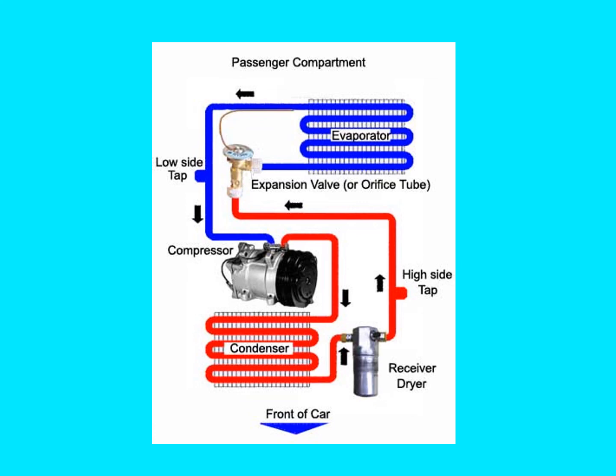The evaporator is going to have airflow across that due to the heater fan. So the fan's pulling ambient air into the evaporator, and because of the temperature change and pressure change, the refrigerant is going to change its state from a low temperature liquid.